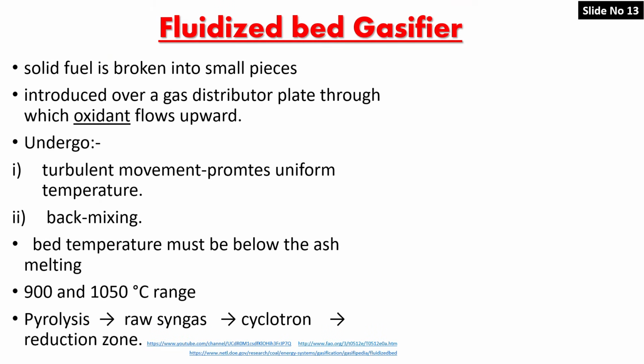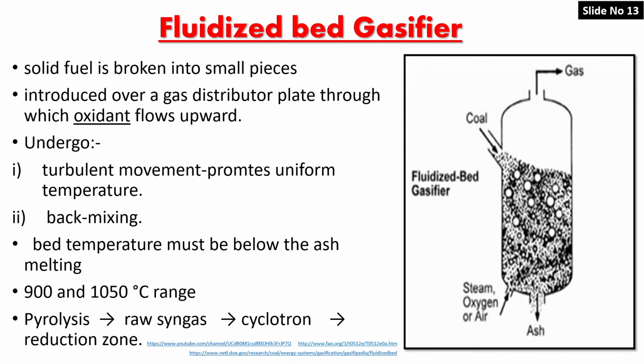Fluidized bed gasifier. In a fluidized bed gasifier, solid fuel is broken into small pieces and introduced over a gas distributor plate through which oxidant flows upward. Hence, the fuel particles are suspended by the upward moving oxidant and undergo turbulent movement including back mixing. It has uniform temperature distribution in the gasification zone.